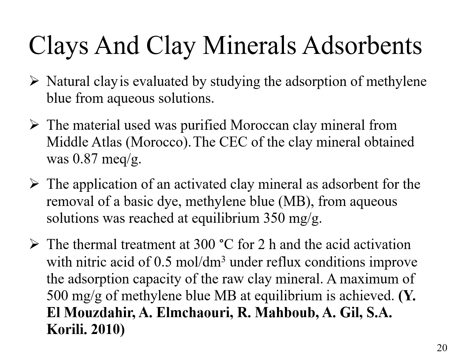Clays and clay minerals as adsorbents. Natural clay was evaluated by studying the adsorption of methylene blue from aqueous solution. The material used was purified Moroccan clay material from the Middle Atlas, Morocco. The CEC of the clay material obtained was 0.2787 milliequivalent per gram. The application of an activated clay mineral as adsorbent for the removal of the basic dye methylene blue from aqueous solution was reached at equilibrium.